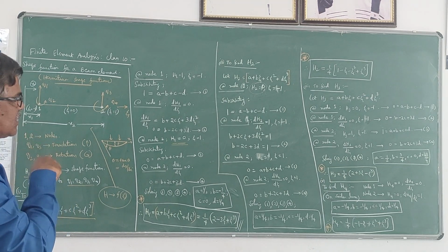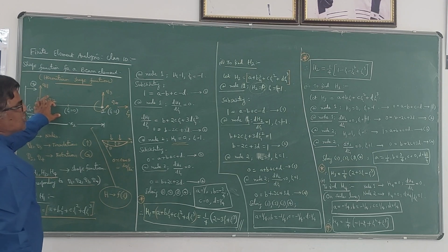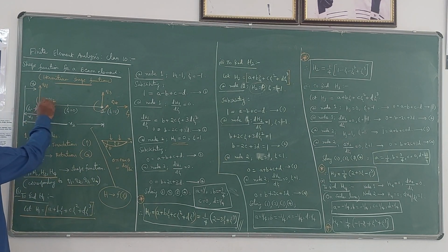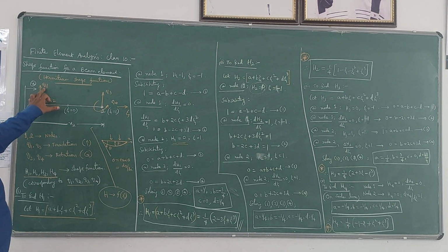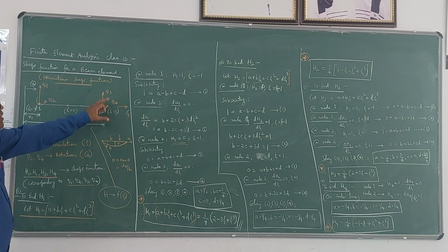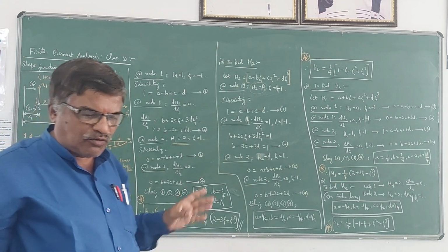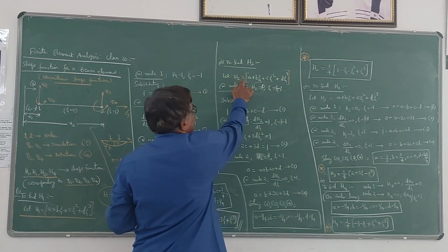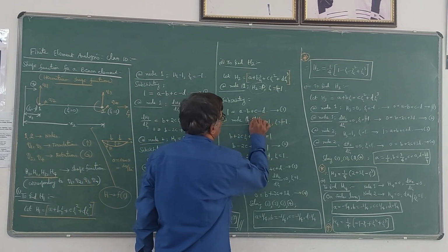Now I am writing for h2. h2 corresponds to this q2. Therefore, q1 I have to make it as 0. So, except q2, the other nodal displacements, corresponding shape function for that nodal displacement, we have to make it 0. So when we are finding h2, please note that the slope at the second node will be equal to 1.